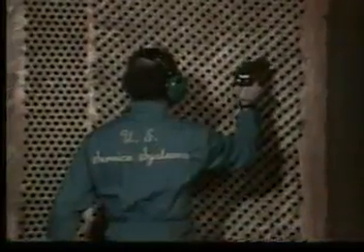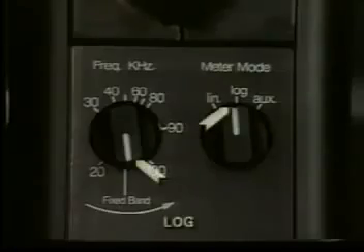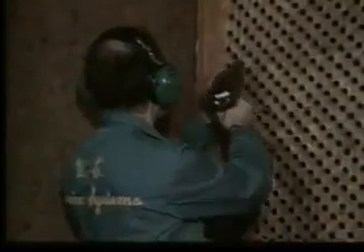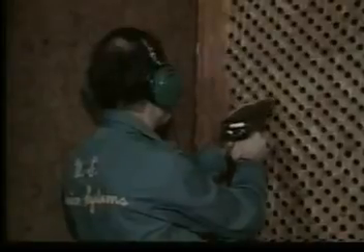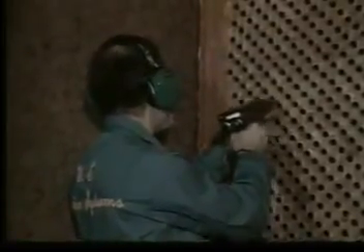Start scanning peripheral tube zones where sounds are loudest. Set the ultraprobe to log and use it in the fixed band position. With the rubber probe, scan a sample tube and adjust the sensitivity to read 50 on the meter. Scan for the loudest deflection in the test zone. To intensify the sound of air in leakage on the inlet side, seal off the outlet tube with plastic wrap.